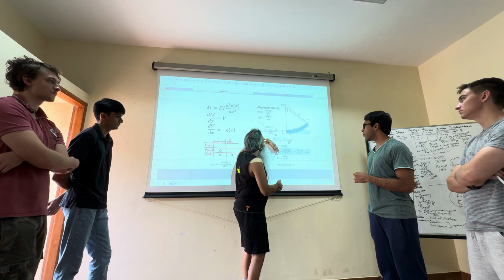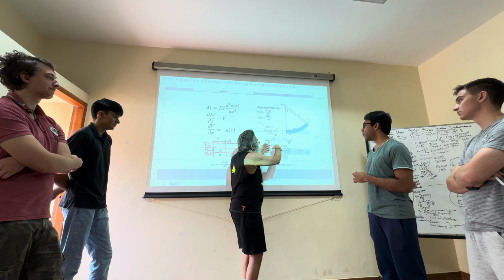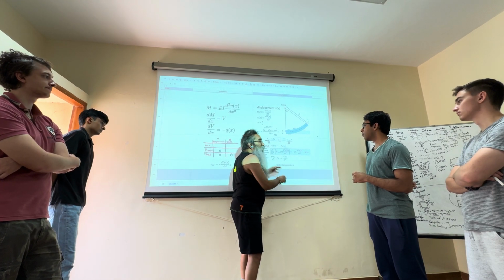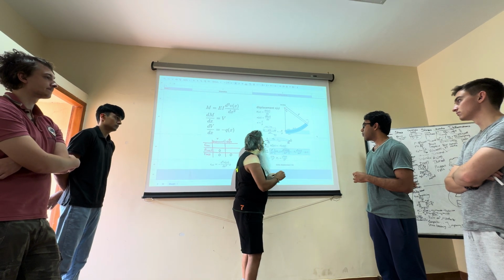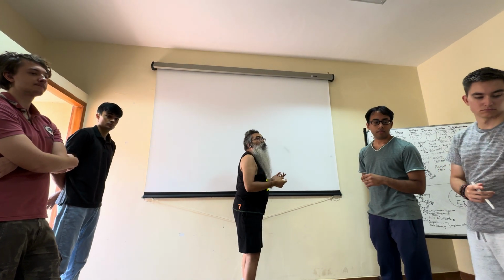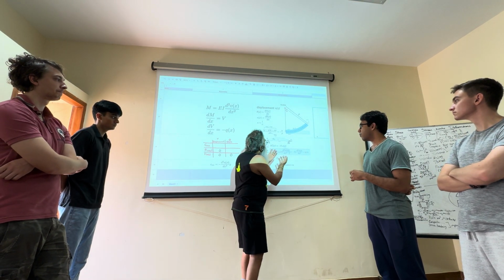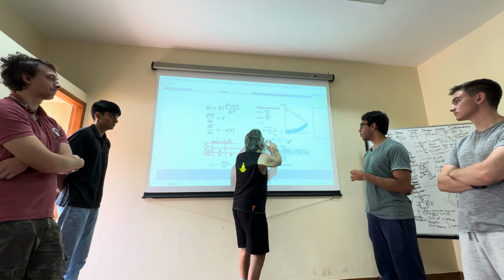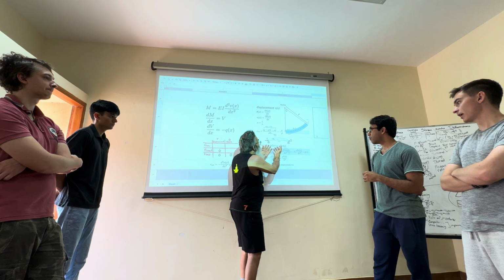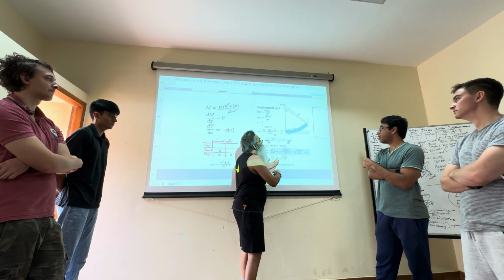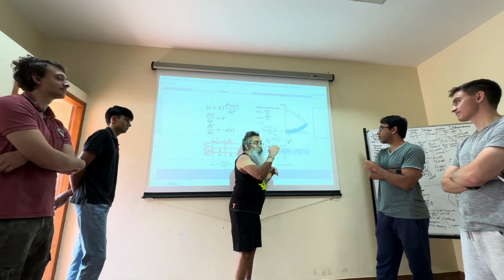The final thing could be, because this may not be just in vacuum, it could be exposed to the atmosphere. So even a small wind, for example, or any small disturbance that is there, just a tap without even actually applying much of a force, all of that can make it move in a particular direction. Otherwise, there's no special reason for this to move either upwards or downwards. So why is it moving in a particular direction is essentially because of these eccentricities, which could be with the load, the material, the geometry, or any external disturbance.